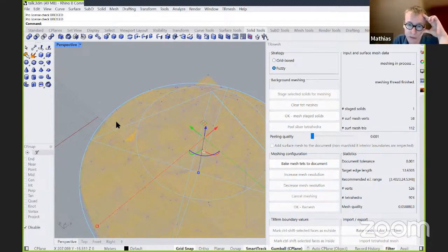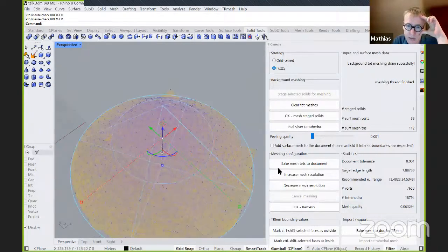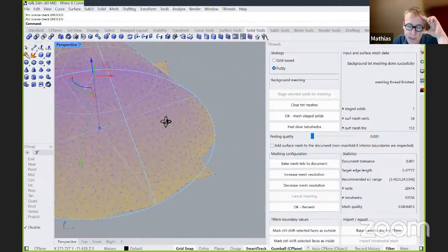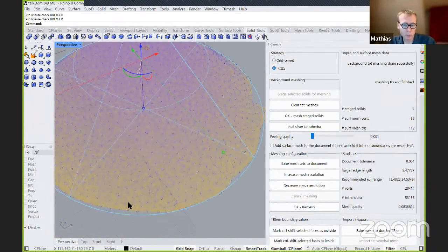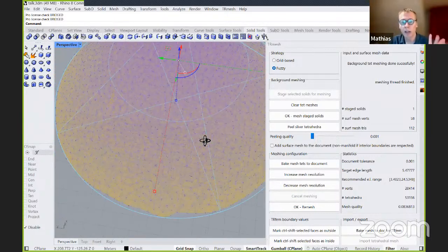So right now the volume is not very well captured because of these protruding dents here, but still you can see that, well, remeshing is of course not going to heal that situation, but the remesher is a finite element remesher that will generate meshes that are very well suited for finite elements, but also very well suited for isosurfacing.